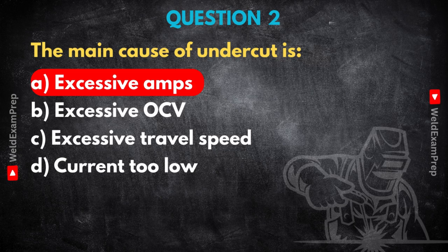That's your undercut. And the problem is it effectively makes the base material thinner right there at the joint. Which weakens it. Exactly. Reduces the cross-sectional area, weakens the joint, makes it more susceptible to stress, potential failure. Plus, like the arc strike, it creates another stress concentration point, though maybe without the same intense localized hardening, usually.